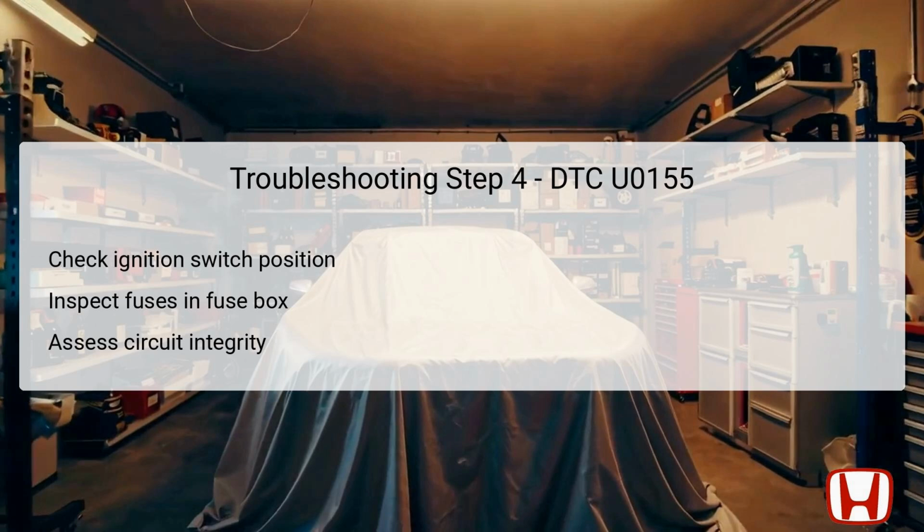If both fuses are intact, you may need to diagnose the circuit for any high resistance or open circuit conditions that could be affecting electrical flow. If one or both fuses are blown, replacing them and checking for shorts to ground will be necessary before proceeding further.